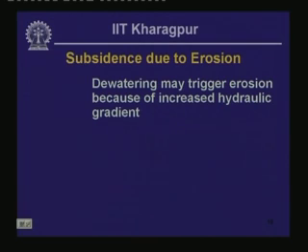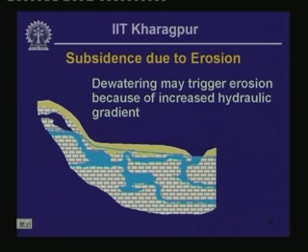So, what we consider here is a karst topography involving limestone, and you can see that the limestone is crisscrossed by solution channels. A part of it is empty near the top left corner of this particular sketch, and a part of it is full as indicated by shading using light blue color, and the location of the groundwater table is indicated by a thick light blue line that more or less follows the topography.